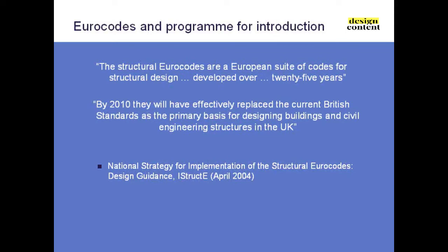So some things are outside the scope of the Eurocodes. For example, nuclear reactors and containments aren't explicitly covered by the Eurocodes because they don't have load combinations, loads for nuclear containments. That said, the latest generation of European pressurised water reactors are being designed effectively to Eurocode 2 with some additional load cases in there. So although they're not within the scope, they can be used for that sort of structure.